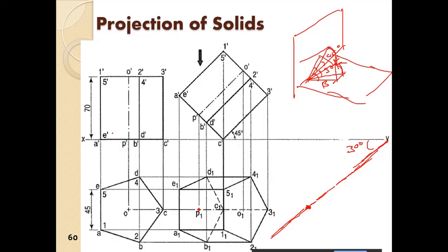Then we will take the axis of the actual prism, so 70 mm. So this is 70 mm, and it is inclined at 30. We will take 70 mm and mark an arc here at 70 mm. So this to this is 70 mm, the axis of the prism. And at this point, we will draw the locus of the trace of the projection of the O dash point.